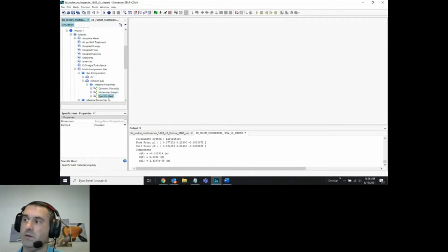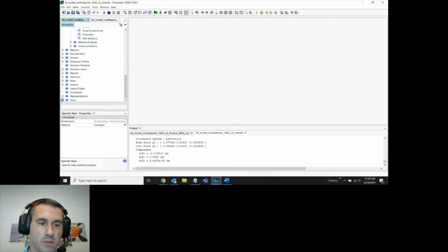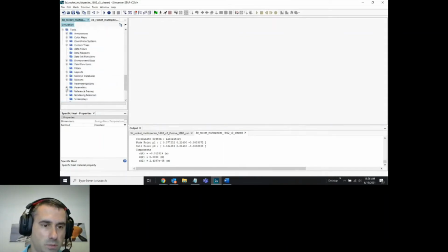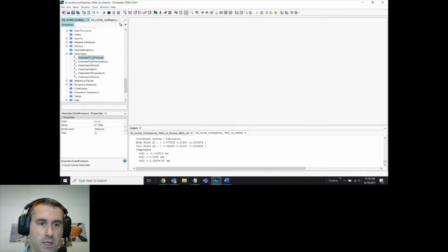Now to get those quantities, there is a NASA chemical equilibrium code called CEA, which is chemical equilibrium with applications. In that application, you can actually determine what those properties are for your engine. Now for the rest of the simulation, you can come down here to Tools, Parameters, and you can change all of these parameters.